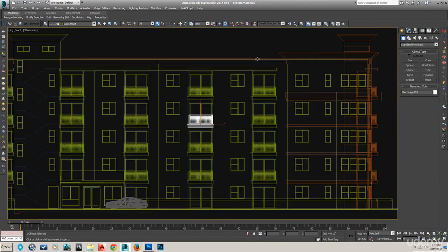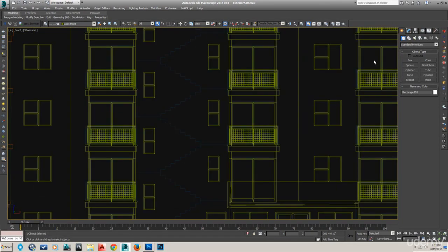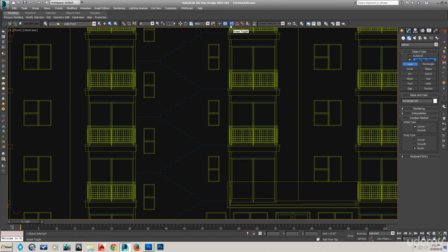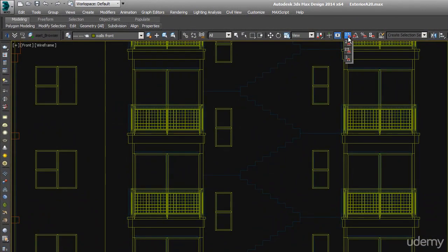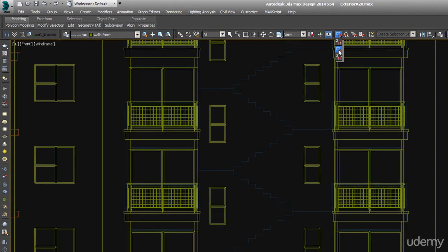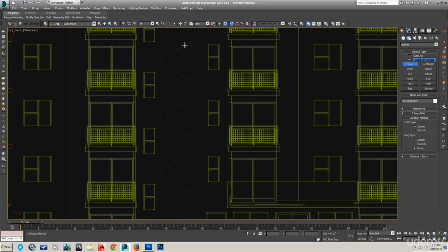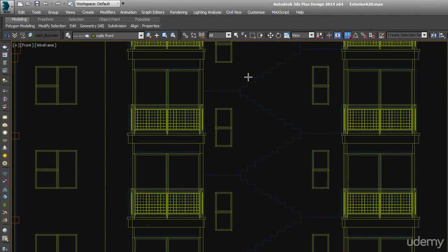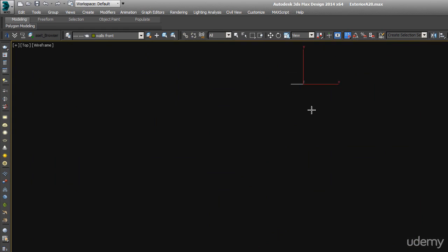Now I can just snap to that CAD, of course. As an example, let's show you, if I go into lines, create line, make sure snap is on, right here, snap toggle, and you want to be in 2.5 snap. Okay, that means it's going to be drawing on the 0 plane, not on the same plane that that CAD is on. So I'll show you what that means. You can snap right to it. And that actually doesn't look like it's working. It's snapping back all the way.